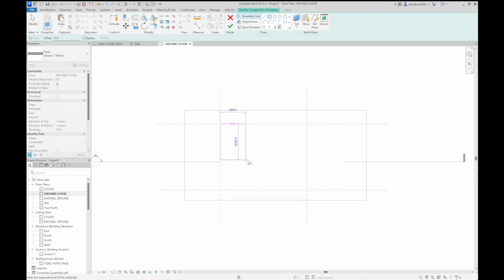and then as I'm drawing, you see it gives me the outline, so I know what it is I'm drawing. And what I'm going to do is snap, bring my cursor down so it snaps to this intersection. Okay, so it's where those two lines intersect each other. And I'm just going to left click, and hit the escape key twice. So these magenta lines here show us where the sketch is.